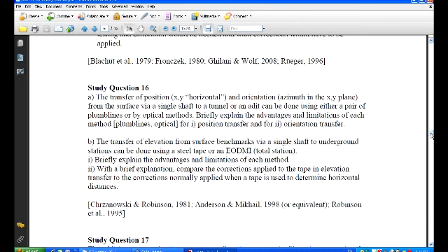This Taylor-Hobson sphere is a special manufacture where the target has been placed at the center of the sphere with a very high tolerance, meaning that it's very accurately placed to the center of the sphere. So regardless of the orientation of the sphere, if you sight at the target, you're always sighting at the center.